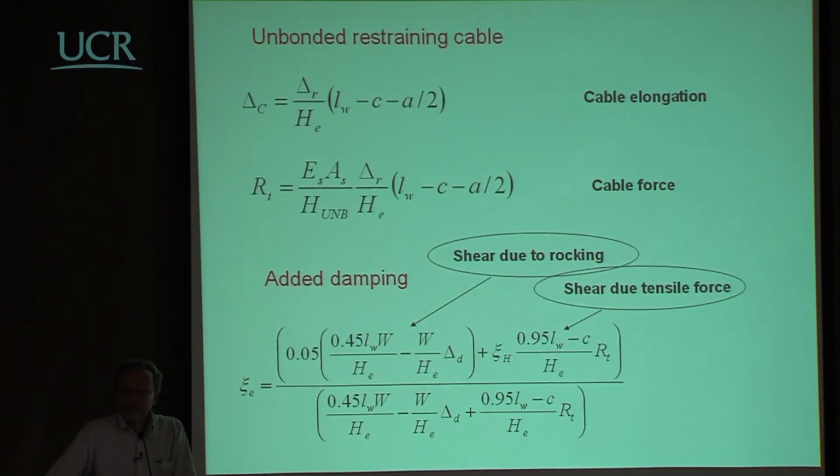You could, instead of using just a cable, connect it through, for example, a steel dissipation device. Or you could also put at the side of the wall one of those hydraulic dampers, and have the wall that rotates and the dampers that open and close, just to dissipate energy, and of course providing a certain retaining force which is constant.